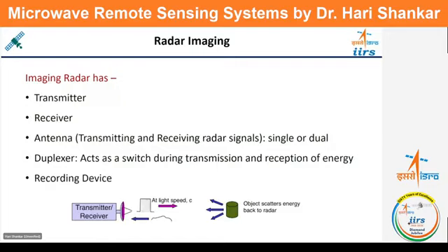Okay. So you can say backward scattering is happening from here to here, but back scattering is only at 180°. So back scattering is basically used for the radar system. Everywhere in the books or in any kind of literature, especially on radar systems, you will see the term back scattering, not backward scattering. Somewhere they can use backward scattering, but not all backward scattering is used. Only the back scattering, which is at 180°, is used for this type of device.